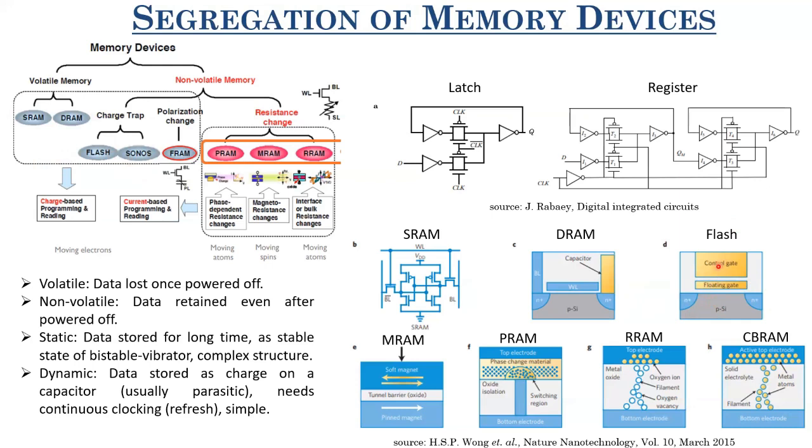Essentially what happens, if you apply a huge voltage on this control gate, then some amount of electrons from this channel are actually pulled to this floating gate or this nitride layer. Now, once there are charges on this floating gate or nitride layer or any storage layer in between your control gate and the channel, then you know from basic semiconductor physics that charges in the oxide layer change the threshold voltage of the MOSFET. So this is essentially a MOSFET where you are changing the charges in the gate oxide layer just by modulating the voltage at the control gate.